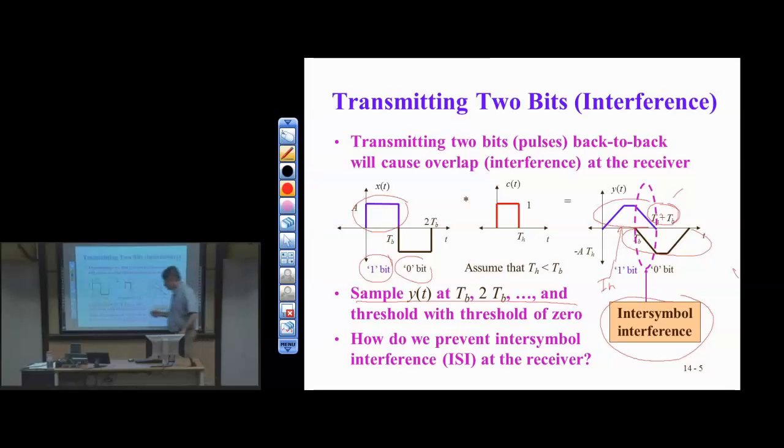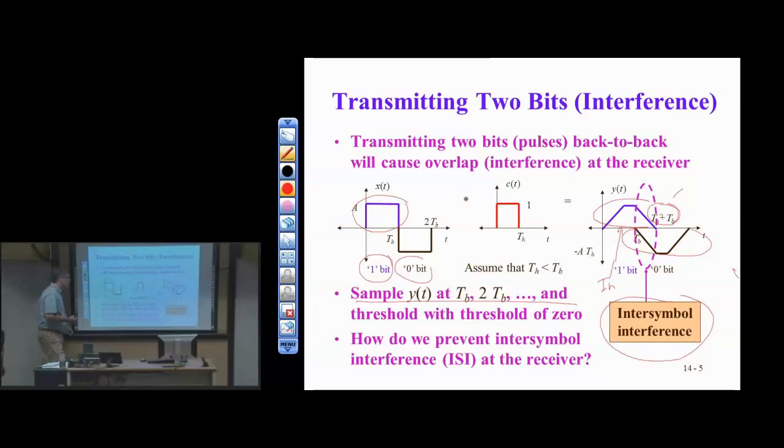Going back to sampling, it would get messed up by noise just because there's a chance that there could be a spike to the other side. That's right, when you're taking just one sample in the symbol period and basing your whole decision of what bit was sent on that one sample, it's really easy to get corrupted by noise. So it's a much better estimate to average over the symbol time and then use that to decide what bit was sent.